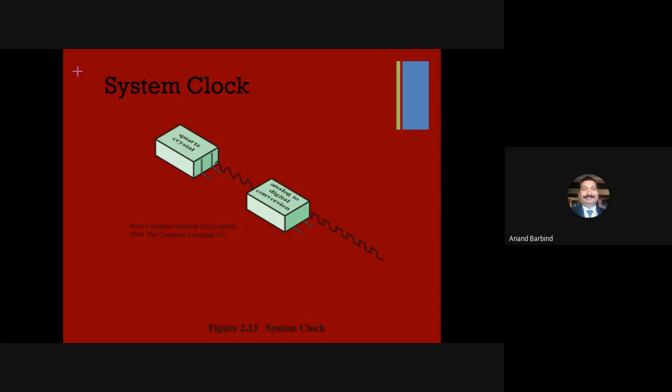With the processor, even the typical frequency is specified. That means if you want the processor to work properly, this is the frequency you must give to it, and a limit is also given that in no case should you give a clock higher than this frequency. If you do, then the operation of that processor or that digital circuit will not be correct, and that circuit will not be reliable. It is not only the upper limit for the sequential logic circuit for the clock.